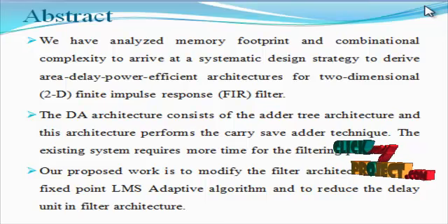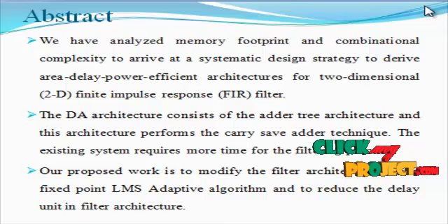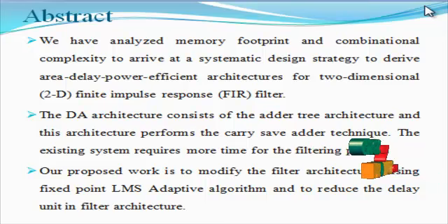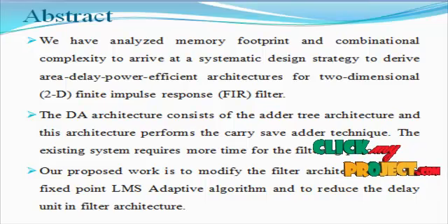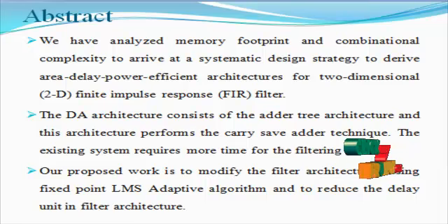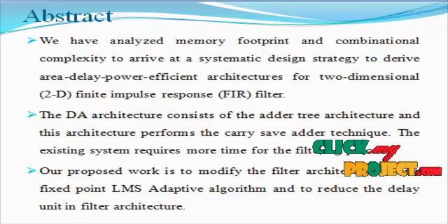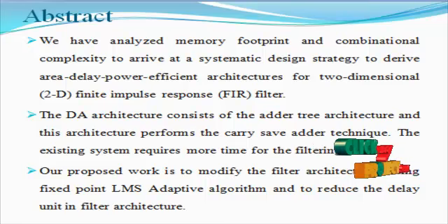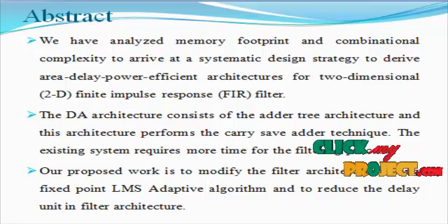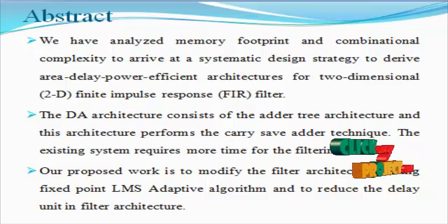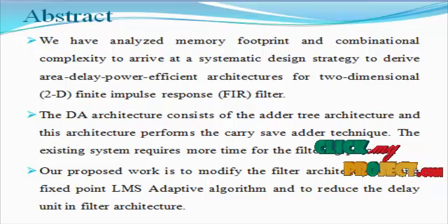Our proposed work modifies the filter architecture using the fixed point LMS adaptive algorithm to reduce the filtering time. We have analyzed the memory footprint and combinational complexity. So we have presented a novel block based structure for separable and non-separable filters with lesser memory footprint, memory sharing and memory usage, along with appropriate scheduling of computation, and to design a storage architecture.